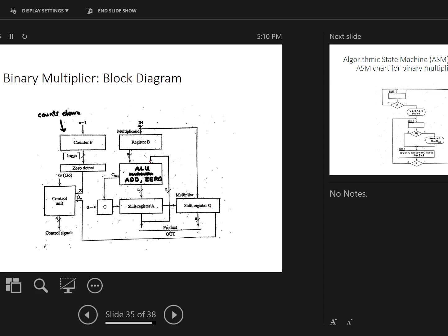in B and Q. We're going to use an ALU for doing arithmetic, an adder essentially, that adds the values up. We're going to have a control unit, or an FSM, that sets up the data path of the control signals to execute what we'd like. And we're also going to use a counter to keep track of our iterations, or how many steps we have in our circuit.